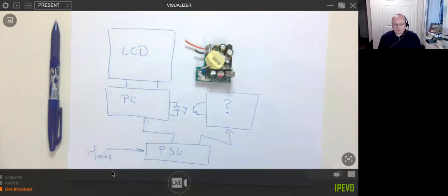Yeah, I had one other thing here. Oh yes, William says, to pass surge test, how much surge current do you need to design for? I think the surge is actually based on voltage, not current. And for a standard power supply, William, they're tested to 500 volt surge, plus or minus 500, I should say. Can't remember how long the burst is. It's a short burst, and they repeat that plus or minus 5 times each, so it's 10 times in total. 1,000 volts, and then 2,000 volts.